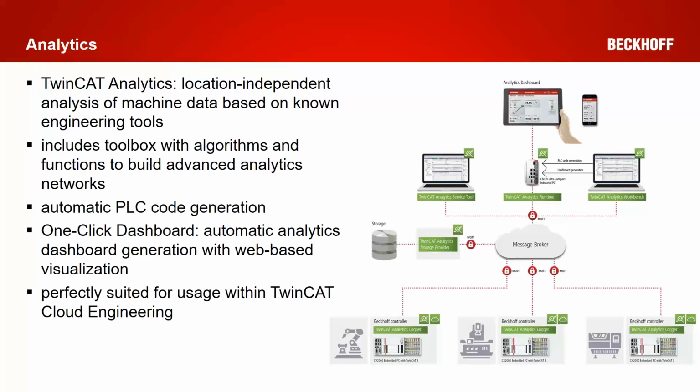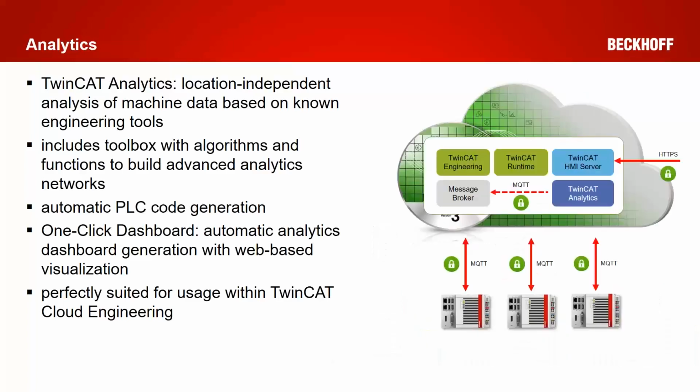So everything is integrated into TwinCAT XAE. Everything is being done either graphically or via IEC 61131 function blocks. And it includes, of course, a toolbox with different algorithms and functions so that you can build advanced analytics networks. And then you can automatically create PLC code out of that in order to have a 24/7 analytics runtime that, of course, can be run and executed on this TwinCAT Cloud Engineering environment.